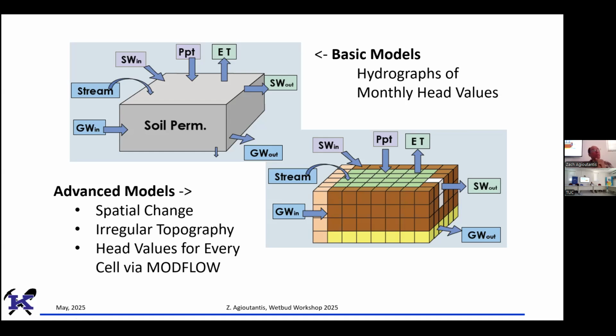Weir. Okay. So a wetland is like a bathtub, but on one end of the bathtub, there is a little dam structure that you can actually regulate its elevation. So by regulating the elevation of the weir, you can keep water in, or if you lower it, water will flow out. So a weir is a small dam structure that's at the end, at the outflow location of the wetland. Okay? Yes.